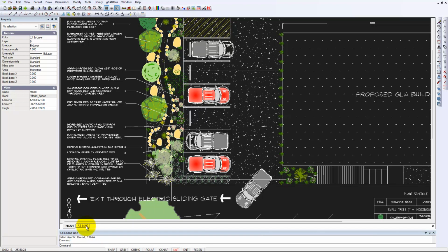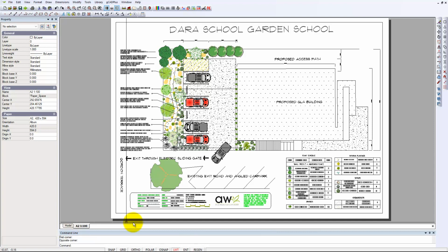However, we can't print accurately to scale doing that. And what I would then do is just insert a scale bar in the design, somewhere convenient where you'd have a north point and a scale bar. And I'll just pause recording and do that. Do not scale off the drawing, but do have your scale bar inside the drawing.